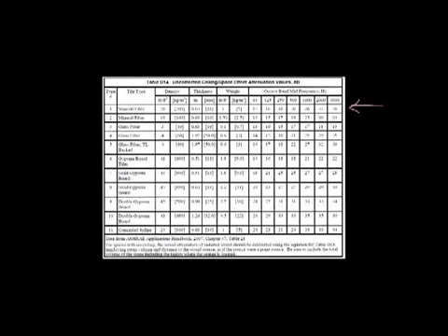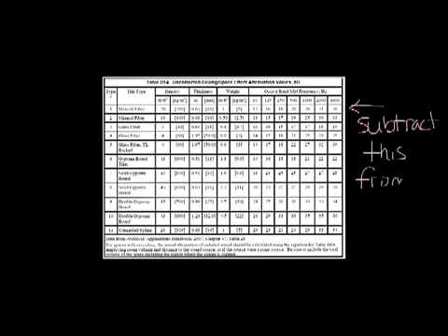The only thing between a VAV box radiated sound and the occupant is usually the ceiling. So knowing how much the sound the ceiling attenuates is very important. All you have to do is select the ceiling type you're using and subtract the attenuation from each octave band. Let me make a little room here.